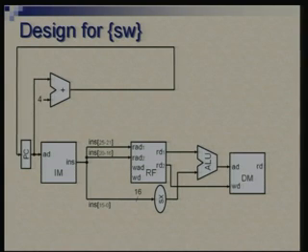Then now let us look at SW alone in isolation. Here the ALU does something different. The ALU does the address calculation, and we bring in the data memory component. So the ALU feeds the address for the data memory, and the data input,